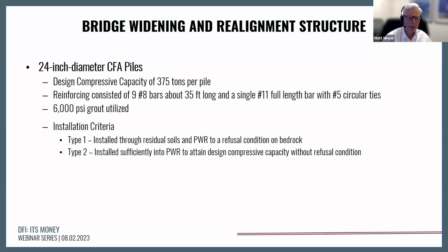The bridge widening, as you remember, I presented before with that second subsurface stratigraphy. Here again, we're using piles similar to the Plaza, a little bit larger in diameter and a little bit higher in capacity compared to the stadium proper. We did use GEC 8 as the framework for implementation of the AugerCast or CFA system below the bridge. That is FHWA's most recent guideline relative to the implementation of this pile type for bridge support.